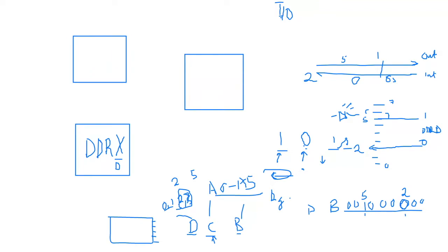Now we are not done yet, because what we want is to connect the push button through a resistor to the 5-volt source. Okay, that's the input pull-up. That's what we want, right? Input pull-up simply means that we have to somehow force this to become 5 volts. So first line we're done. We've just set it as an input. Now we want to force it to become 5 volts.